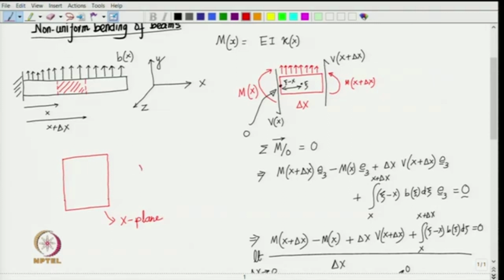So, we have sigma xx here as the normal component of traction, and this arises due to bending of beams. Can you recall that this was equal to minus of bending moment M at the cross section x times y, where y is the distance from the neutral axis, divided by Izz, is it not?